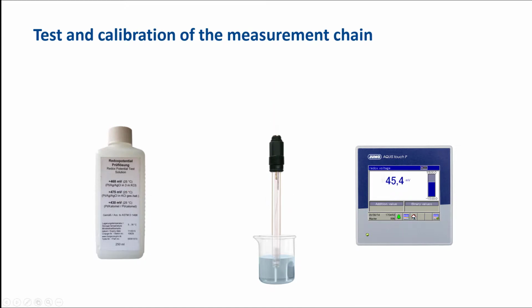If the measured value reaches its final value very slowly, the reason may be the passivation of the metal. The passivation is counteracted by treating the metal surface, for example by polishing with a cloth or using cleaning agents. If the measurement in the test solution shows deviations, this is corrected by a 0-point calibration.